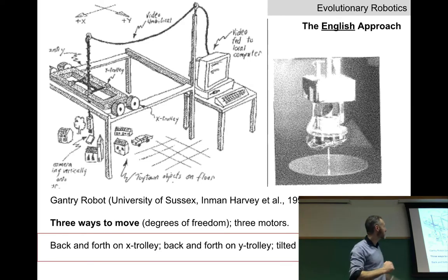Hanging down through the center of the smaller trolley is an inverted periscope that you see here. So we have a camera that's actually pointing down. That's the camera housing here. And the camera is pointing down, and it's pointed at a small dental mirror that's angled at 45 degrees. This is why it's the periscope. And the dental mirror can rotate around its long axis. So the camera is pointing down, but because of the mirror going at 45 degrees, it can see off to the side, and as the dental mirror turns, the robot can sort of see all 360 degrees around itself.